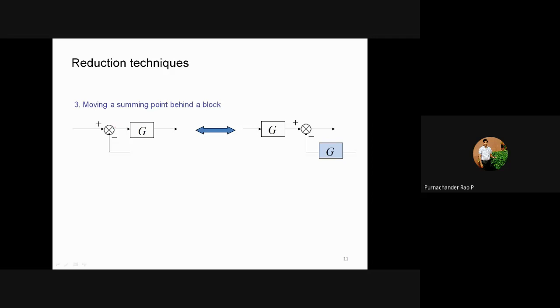Now, moving the summing point behind the block. Here the summing point is before the block. Now I need to move it ahead of the block.